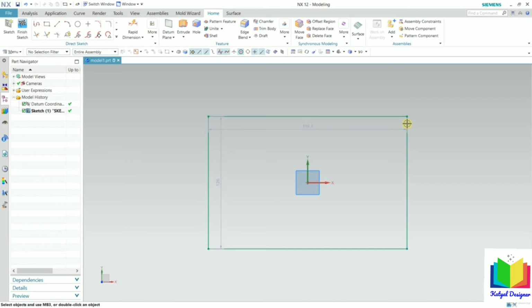For this we have many options in NX. First thing we can do is use the keyboard. Let's say I want to delete this line. Just left click onto this line and then here we can see the option that is delete, and the shortcut key for this, it is highlighting Ctrl+D. So we can delete this from here, click on this delete. And now we can see the line is deleted. Similarly, if I select this line and then press the delete key from the keyboard, we can also delete the line. I undo this, so press Ctrl+Z.